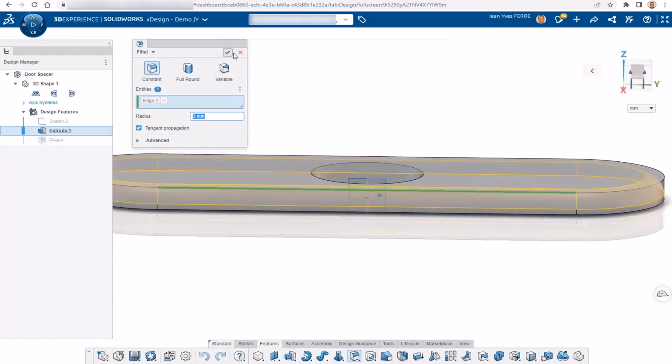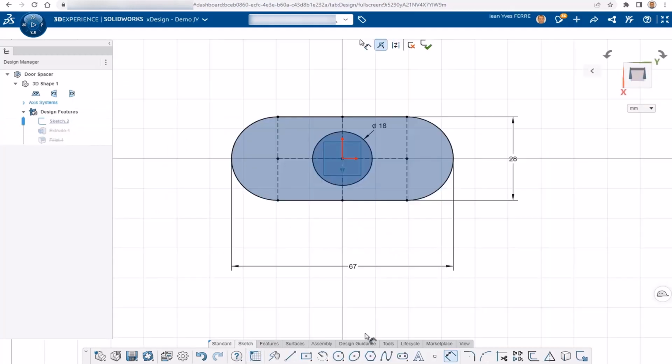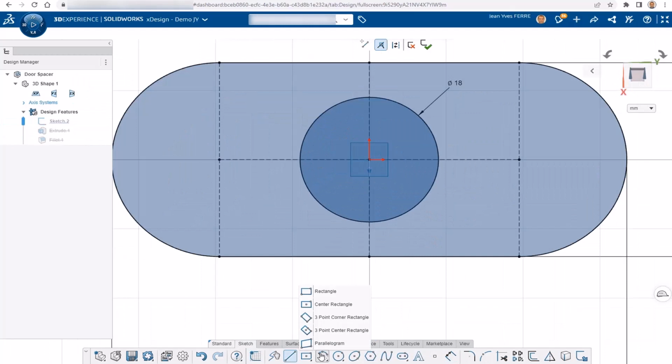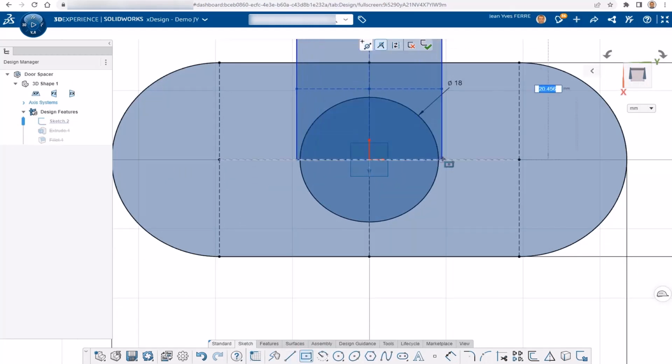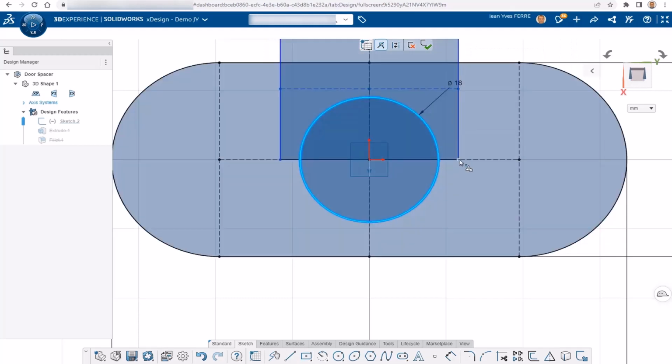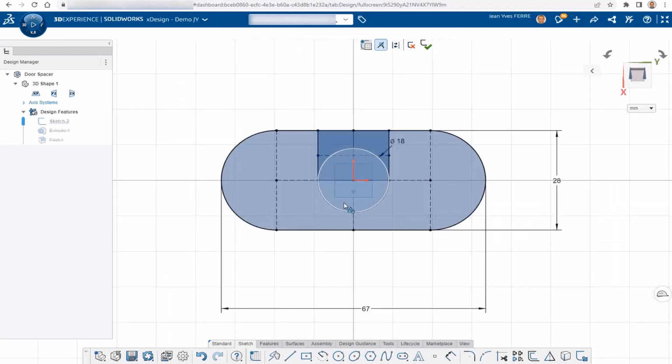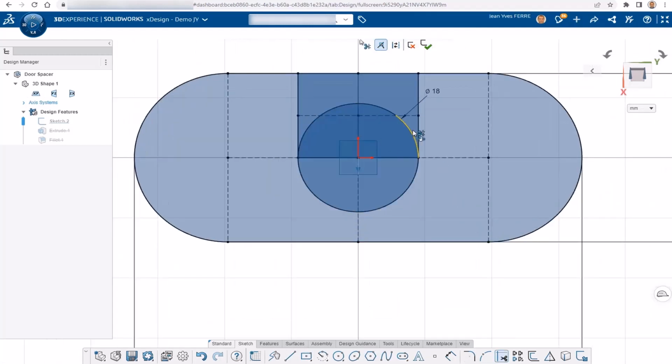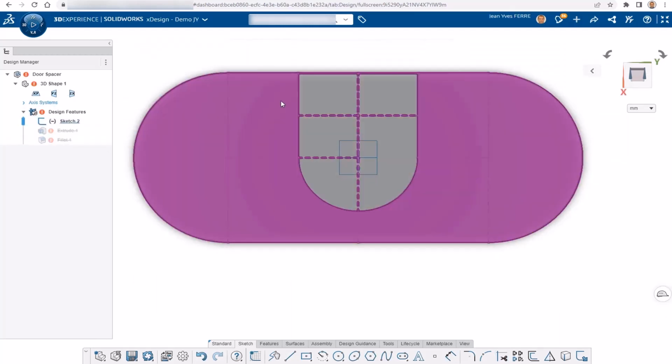As the handle cannot be removed from the assembly, I need to create an opening from the part. For that, I just change existing sketch to add the relevant edges. Look how sketch entities change color when they are fully defined with dimensions and geometric relations. It is important to make sure changes to other dimensions will not produce strange geometry. We will see what could happen later.